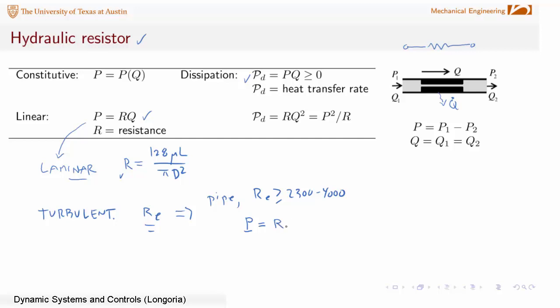So, for example, you might have another coefficient, that's not necessarily the same as this r. But now that relationship with flow rate can become quadratic. And actually, often instead of using q squared, we'll write this as q times the absolute value of q, and there are some benefits to doing that.